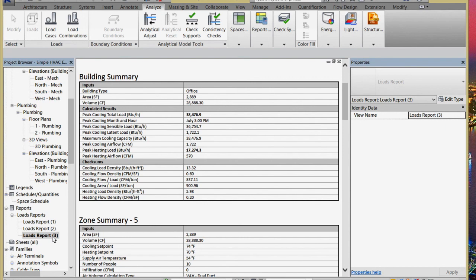In terms of sizing a heating or cooling plant, there's a pretty significant difference in what's going on. So here's my caution, or what I really want to drive home about this whole calculator: if you're going to use it, go through and make sure the assumptions are fairly close to what you really want in the building, because it can lead you to something that's almost 3 times off if you just use the default assumptions.